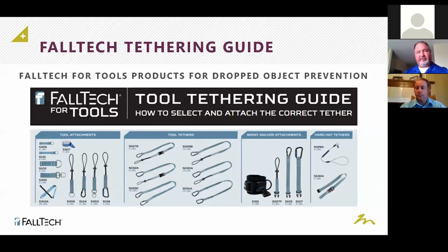And another big thing is the wrist attachment. The important thing about that is, when we're on a construction site, we talk about 100% tie off. The easiest way for me to explain 100% tie off is to think of when you were a kid, or if you have kids, doing the monkey bars. They're connected on both hands. They disconnect, connect to another one, connect, disconnect. That is 100% tie off. At any given time, you cannot fall because you are connected all the time.